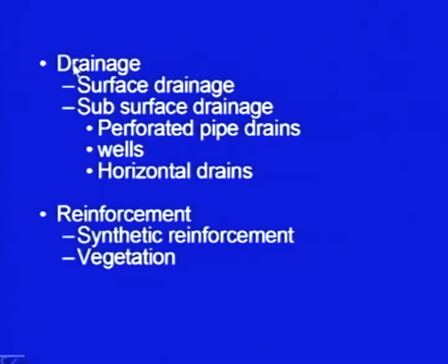Then drainage: you can improve the drainage. Water pressure is the biggest enemy in the case of slopes. Good drainage can be provided, and drainage will reduce the water pressure and effective stresses will increase. Once the effective stresses increase, the shear strength is automatically going to increase. So drainage is one of the very effective measures, and it can be provided at the surface, where surface drains can be provided.